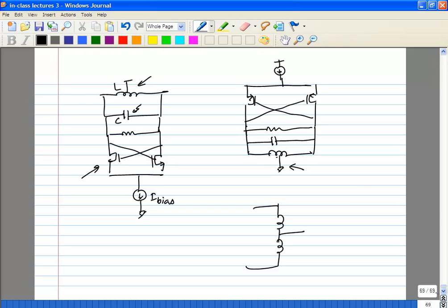The Q of the capacitor is more like 30, 40. Especially if you have a good passive capacitor, it can be pretty high. That is why you almost always consider the resistance of the inductance to dominate the overall. But there are very specific cases where the resistance of the capacitance can matter, and that depends on how you choose your inductor and capacitor values.